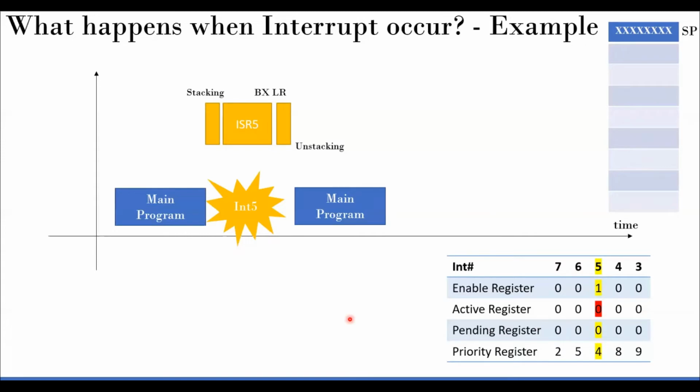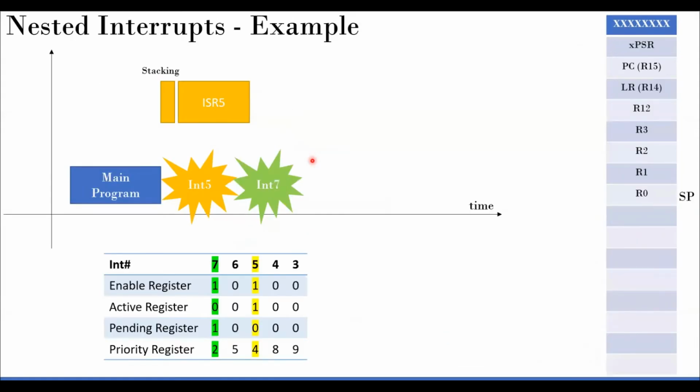Moving forward, of course, the stack pointer will go back up to the original location. Now this is a complicated case, because you can think of it as something like you are already executing an interrupt and suddenly another interrupt comes, which is very usual, right? Because our system is very complex. An embedded system has so many interrupts coming together. But then something has to be done. Let's see that, from the previous case.